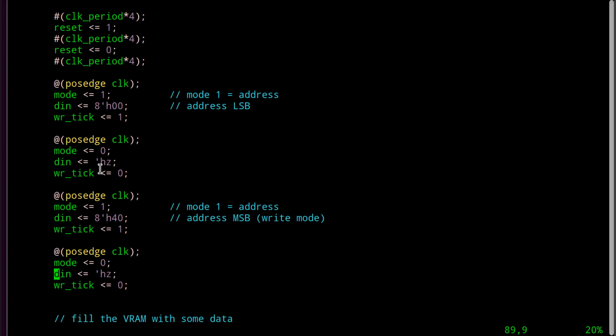You can remove this and it should work just as well either way, even if these are back-to-back, which I would argue is an absolute impossibility with our Z80, even running it at a super fast speed like 25 megahertz, because the Z80 takes many clock periods to finish any individual instruction, and this is going to be an out instruction followed by another out instruction from the CPU in order to create these two mode 1 writes using the output instruction. So many a clock will actually be idle between these two things when we run it on the real CPU. Okay, so I want to make sure it works if it goes idle in between is my point.